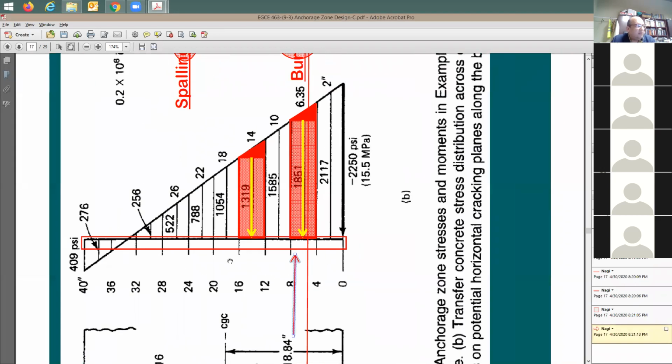Now, do you know how to do the moment diagram for this? Yeah. Now take this force times this distance. Let's say here's a section that I'd like to figure out the moment for. Take this force times this, plus this times this, plus. Or let's say if I'd like to work on this section here, I have the option either to look on the right or to look at the left. In this solved example, when they cut any section, they look below, which means on the right side.